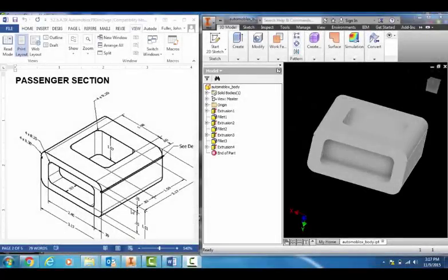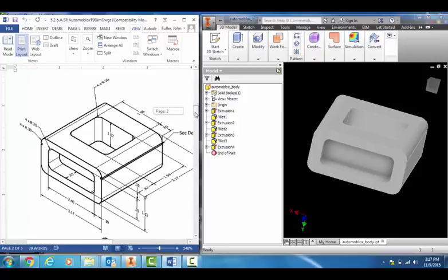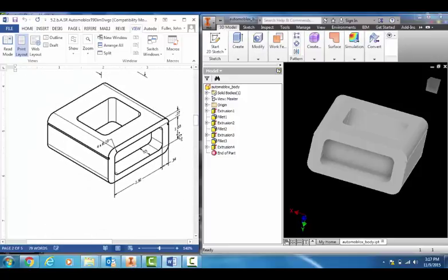Okay, let's come back to our assignment here. Alright, and scroll down here. We have one more hollow piece to make. Alright, right here. Now notice it's got a length of 2.5 inches, a height here of 1 inch. It's 0.27 inches from the top and 0.34 inches from the side. And finally, it's extruded here, or the depth of this hollow piece is 0.57 inches. Okay, so let's go ahead and start creating that.